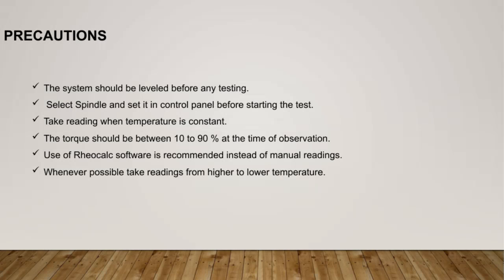Before starting any testing, the system must be properly leveled. This is a crucial step to ensure accurate and reliable results. Next, you'll want to select the spindle and set it in the control panel before initiating the test. Proper setup here helps maintain consistency throughout your measurements.